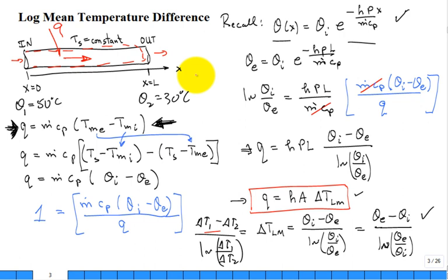So you take that energy balance for the whole system, you have a temperature distribution, you have a form of the equation that you want, and then you force this and this to package up to make the equation like you want. The conclusion is that this is the appropriate way to express a temperature difference. It's called the log mean temperature difference.